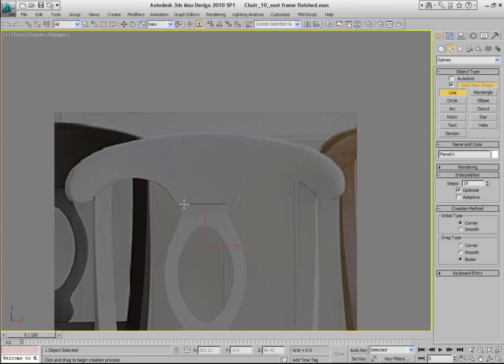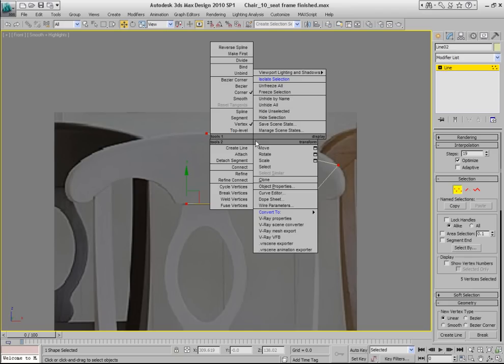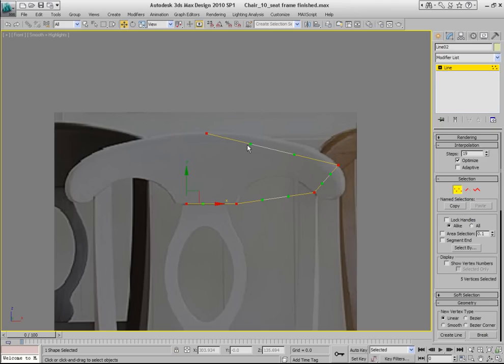I usually just start with the straight lines and build something like that, so that I can go to Modify Panel and manually adjust all the vertices of this object to give all the segments the right curvature. And this is something relatively simple and fast, so let me just go ahead and take 5 seconds to do it. All right, something like this looks good.